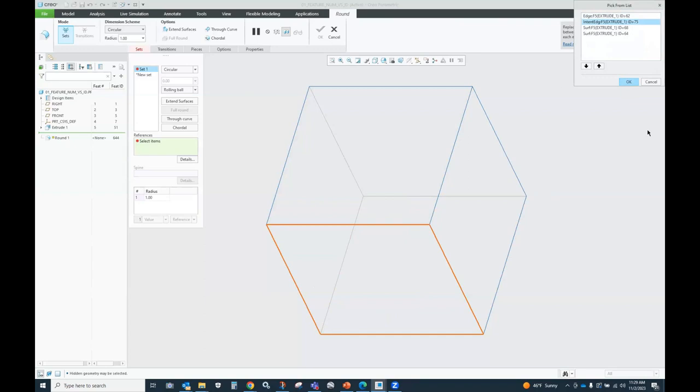Okay, same thing with the back. If I pick on my pick from list, you'll see there's an intent selection in the back. So these things are all over the place. And most often, they're a better choice. And they won't fail because they don't belong to geometry. So it's very hard to delete those.